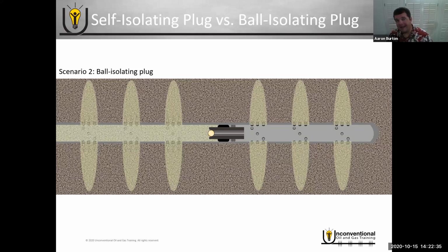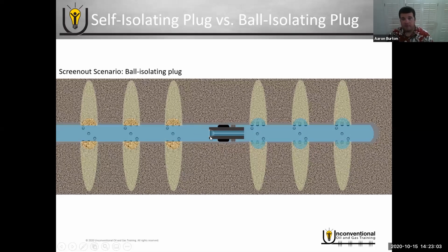So it doesn't happen as often anymore, but there's also another scenario where the ball isolating plug comes into play, and that's with screen outs. Just to remind you, we talked about screen outs yesterday. That's when you've pumped too much sand, too much volume of sand all at once, and you can no longer pump into the wellbore. It blocks off where you're trying to fracture and then backs up the well.